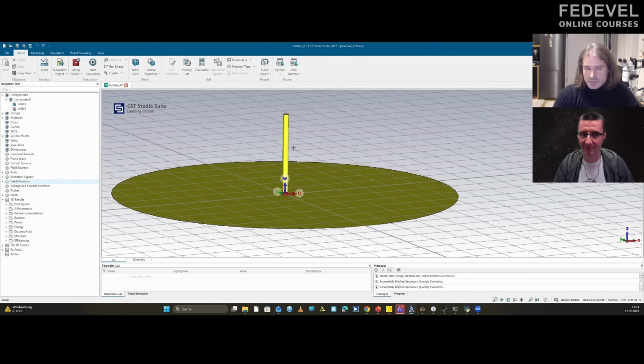And sometimes you get an antenna which is not very robust, because the components are very sensitive. One change in those components can also change the resonance frequency. So you must be careful with matching. Not always is it good to do matching.